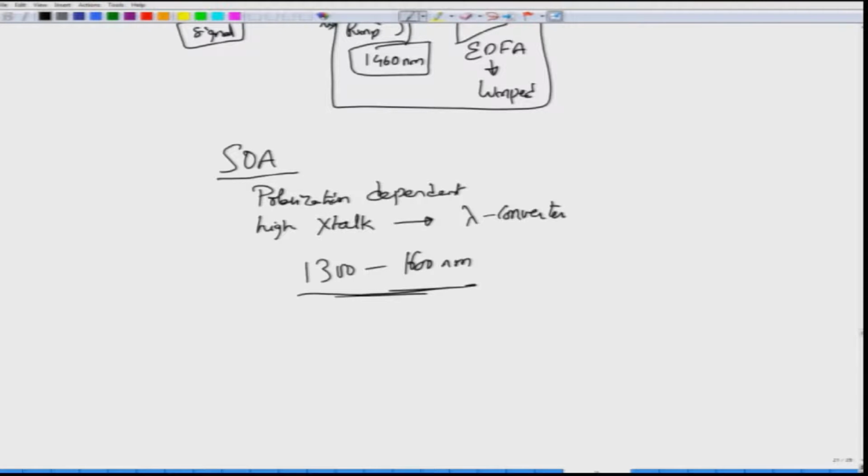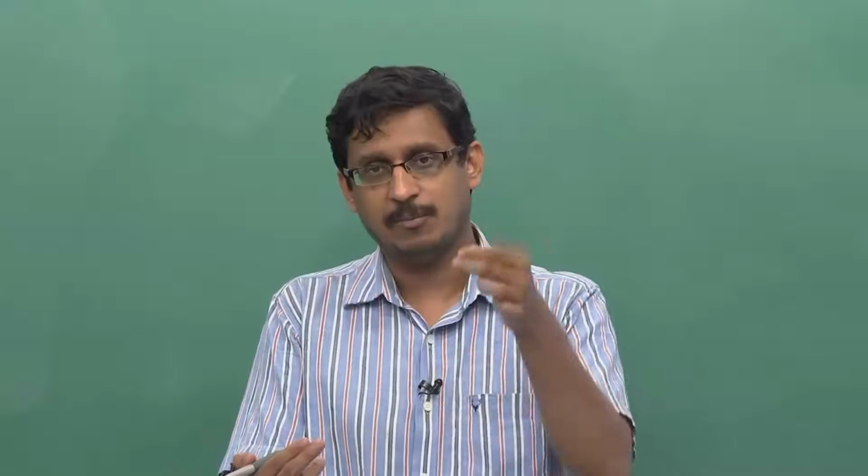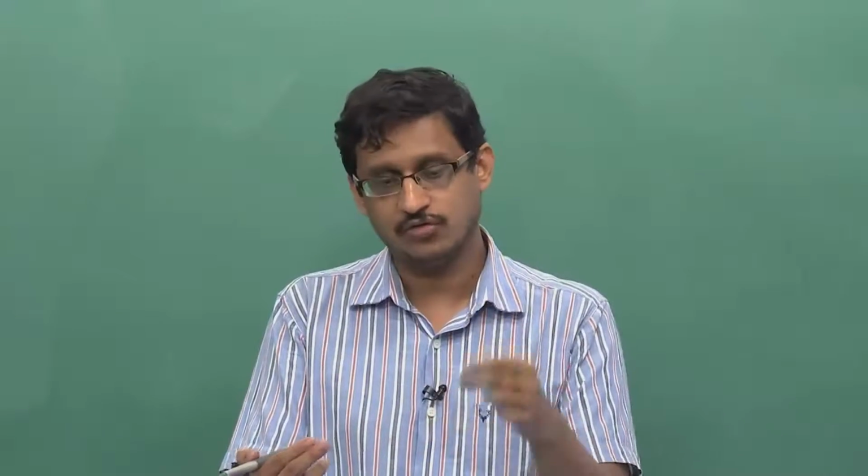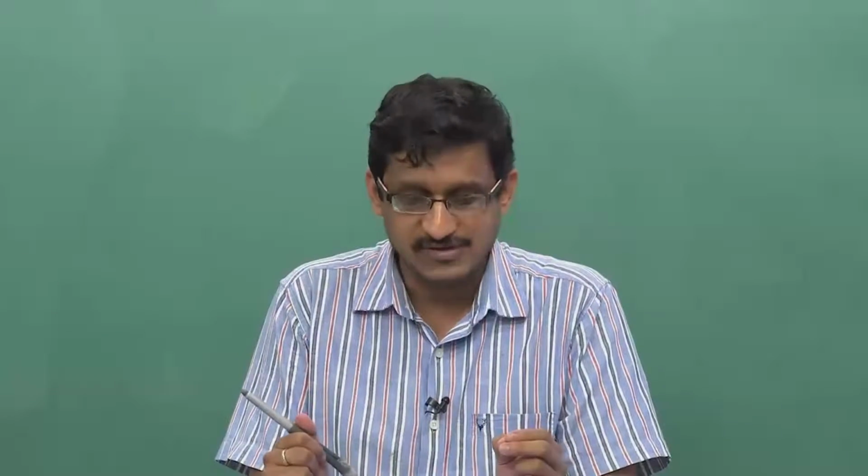The construction of an SOA is very similar to a double heterostructure laser diode that we actually talked about. The pump is the current, and the pump is in the transverse direction. Everything that we talked about for lasers actually holds for semiconductor optical amplifiers as well.